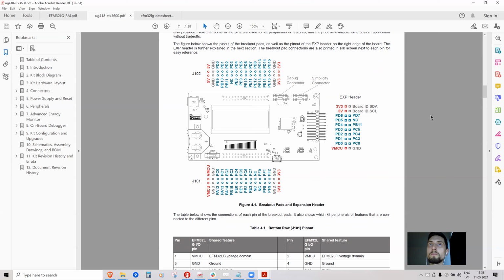And between port C, pin 6. So in the newer version, it looks like it's a no connection pin, which is not good. On older development kits, there's port D7 and port C6, and they are connected together. I don't know if you have it, but there's a jumper which you need to leave on between port D7 and port C6. I'll try to find an older datasheet.